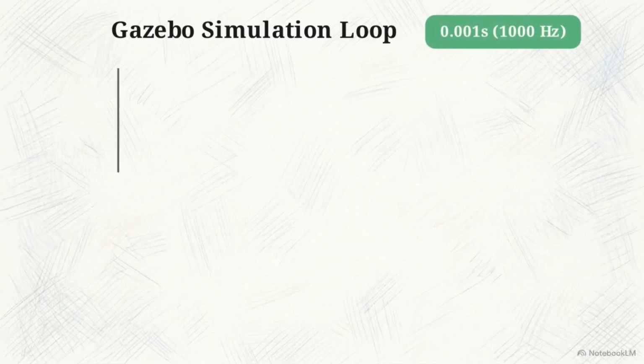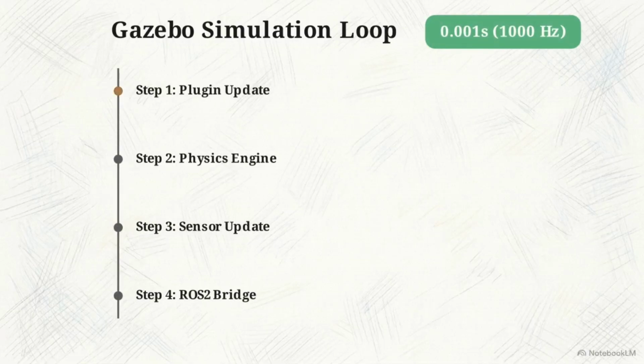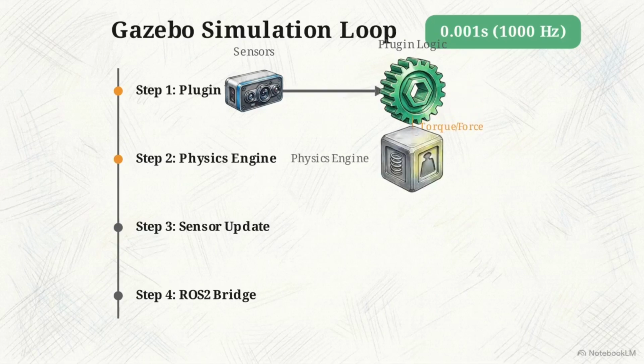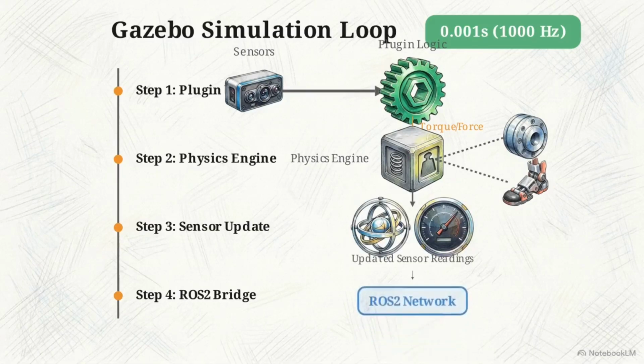Finally, the simulator updates sensor readings and publishes data back to ROS. Then the cycle repeats immediately, because your C++ code executes in step 1 before the physics engine moves. You are effectively operating with zero latency relative to the simulation state. This 1000 Hz lock step avoids the jitter of asynchronous ROS2 messages, which arrive at random intervals, while the simulator resolves the next frame of reality.